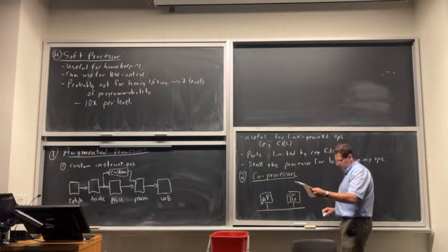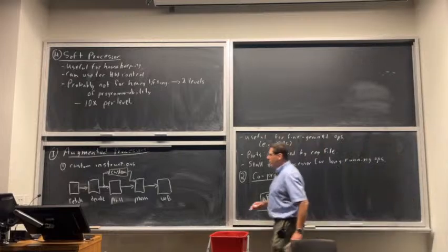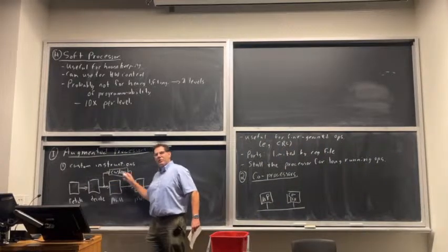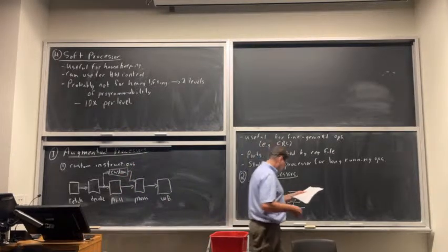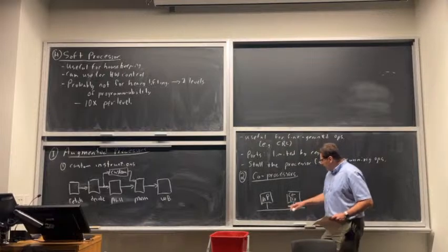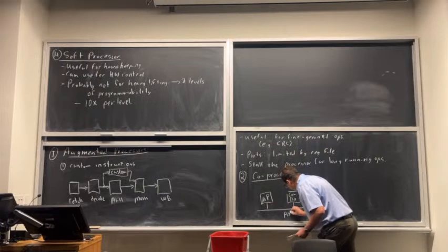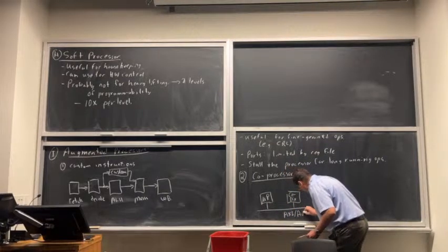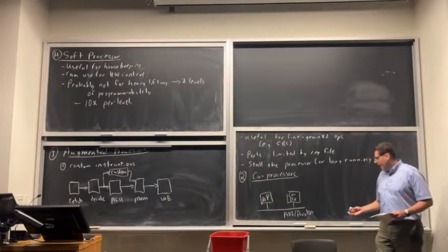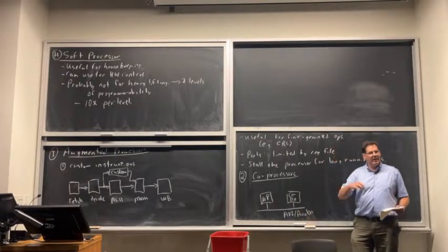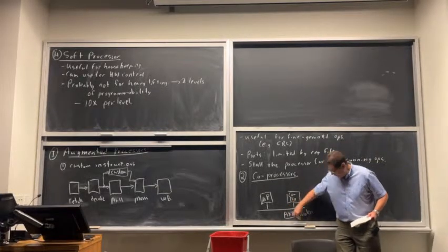So a coprocessor, it's not as tied to the processor. This is really coupled. We actually hooked it into the processor pipeline. So it's very, very closely coupled to the processor. Coprocessor, we communicate over a standard bus. So two main ones are AXI, which is ARM's bus standard, which Xilinx uses, or Avalon, which Intel Altera made and use, although I think Intel is now also supporting AXI quite a bit too.